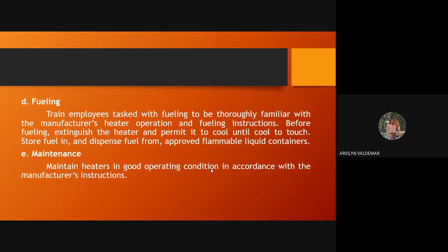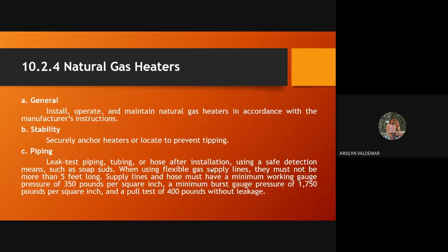Store fuel in and dispense fuel from approved flammable liquid containers. For maintenance, maintain heaters in good operating condition in accordance with the manufacturer's instructions. So, for natural gas heaters, in general, install, operate, and maintain natural gas heaters in accordance with the manufacturer's instructions. Next is stability. Securely anchor heaters or locate to prevent tipping.